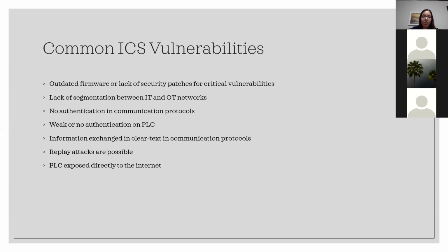The PLC may have ports exposed directly to the internet. With these newer internet protocols, like Modbus TCP, these ports often get exposed directly to the internet. And that means anyone can send commands to the PLC.